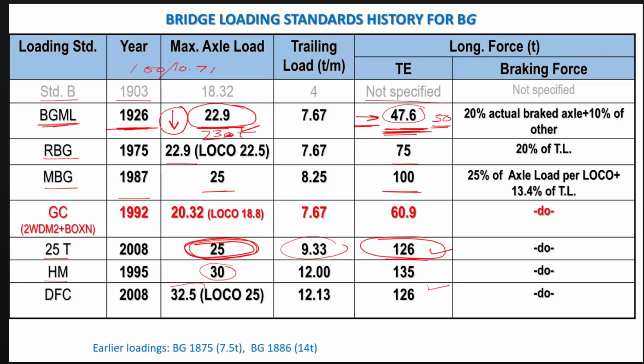In that case, for the substructure, we require the drawing. If we don't have the drawings, we have to make a borehole up to the foundation level. We need to get the actual profile, because the most critical section is just our foundation bed, either at the founding level or above where our section is reduced. That is the most critical level, so we have to check there, where the maximum stresses come.